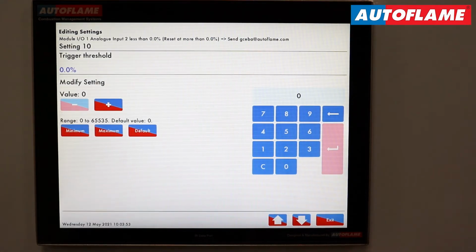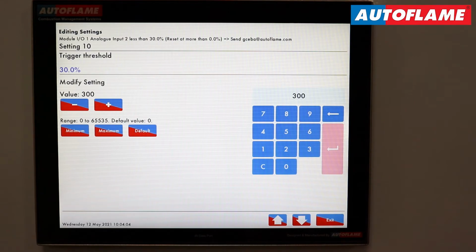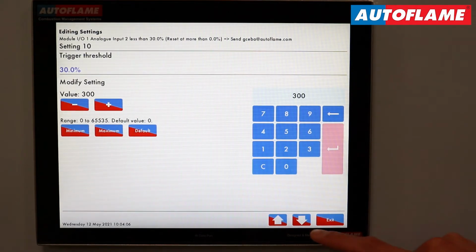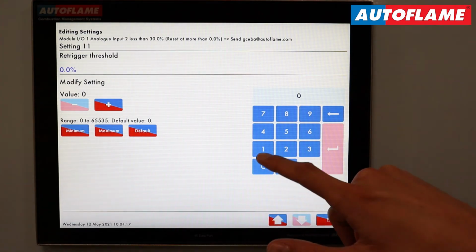What should be the trigger threshold? If it's a 100 millimeter tank, when the water level drops to 30 mil, then we would like this to be triggered, and we want the system to be back up and running or in normal stage if the water level goes back up to normal set point. So let's say the pump should go off at 110 millimeter.